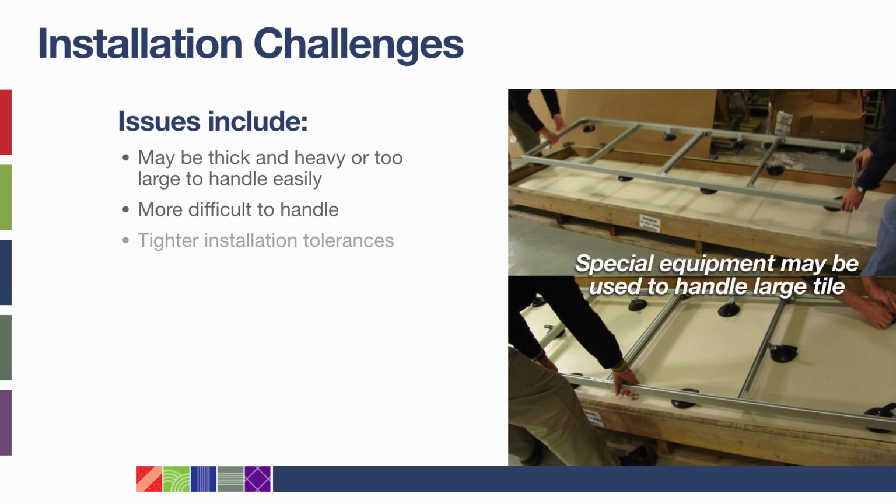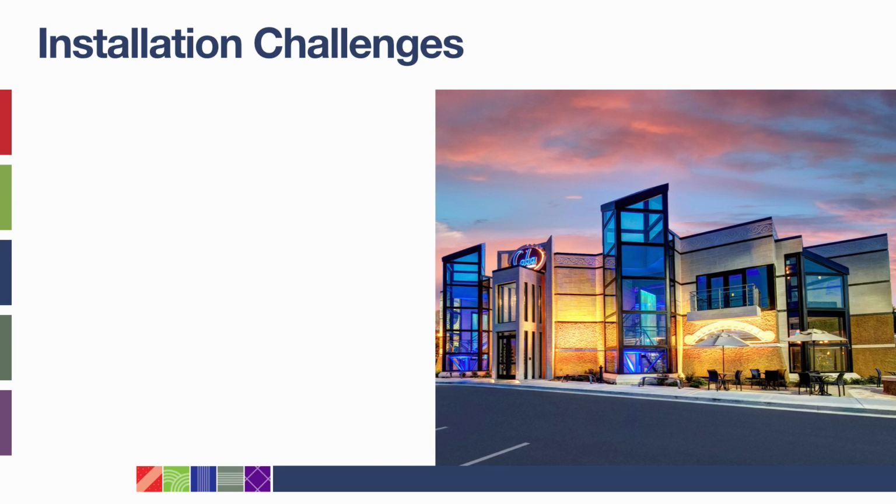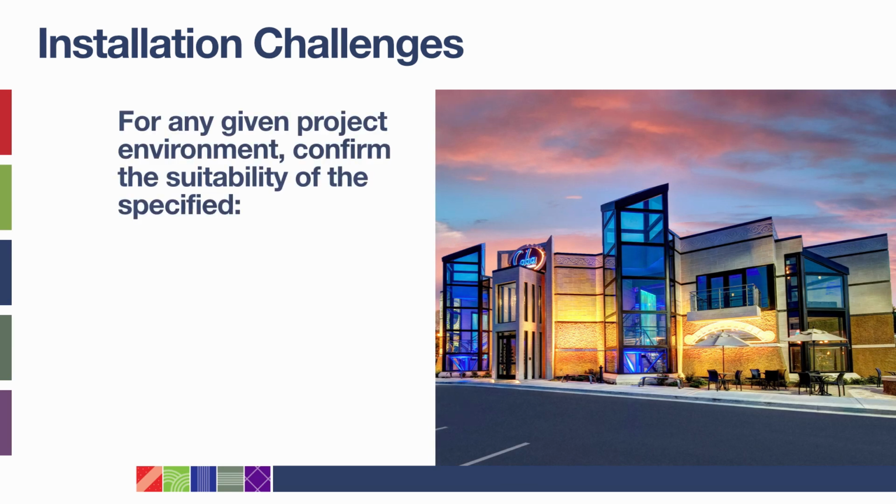They require tighter installation tolerances and are more expensive to both purchase and repair. To avoid costly issues down the road, you must take appropriate precautions when working with large format tile. Given the higher potential for installation challenges, it's very important to take into account a project's environment when choosing tile or stone type to ensure that your installation performs as expected and has a long service life.